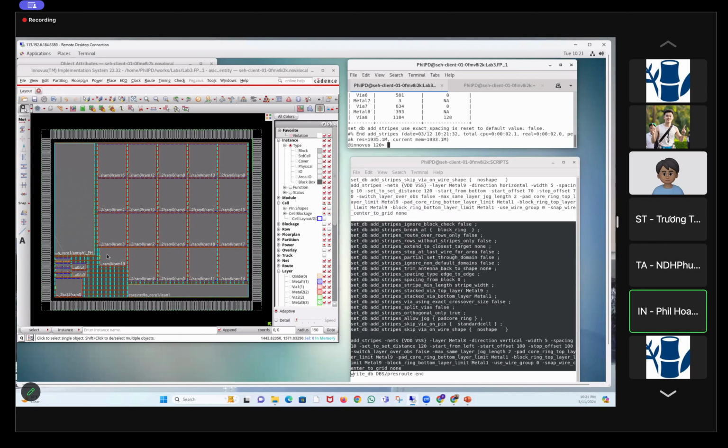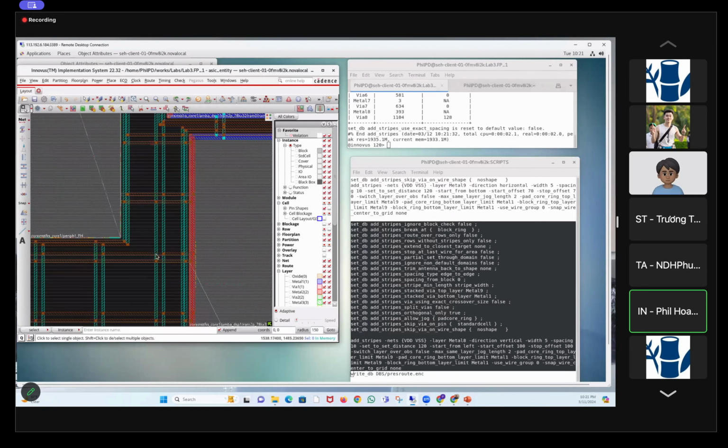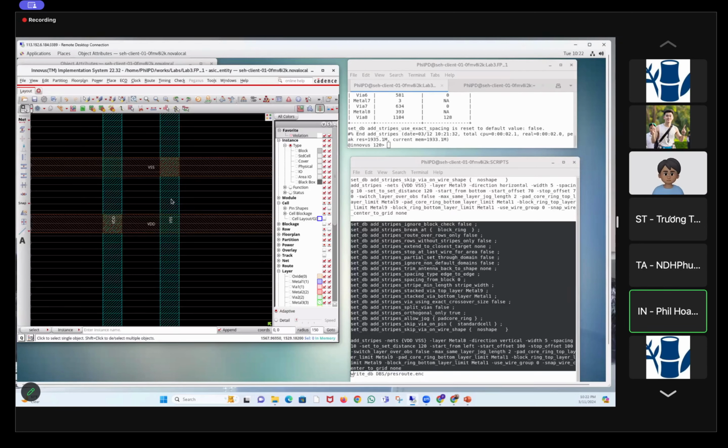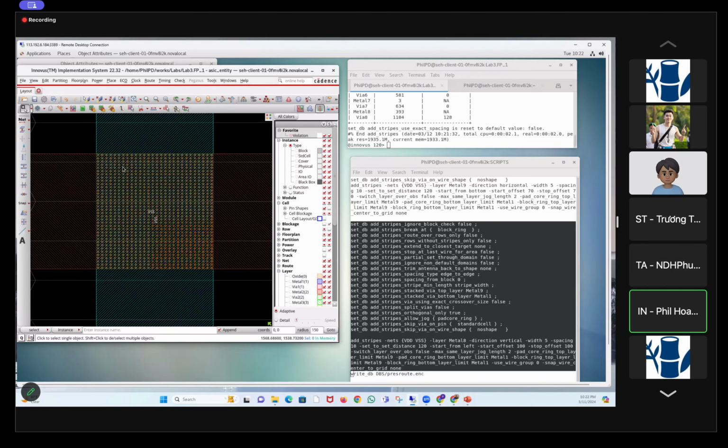We're going to analyze them, why they're needed and all. So you can see metal 8 is built vertically. Some of them are already there in the ring. And then you see whenever metal 8 crosses metal 9, it vias to the metal 9, right? If VSS sees a cross section with VSS, it just puts vias in here. Right, you see vias.